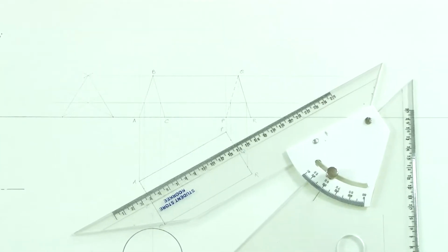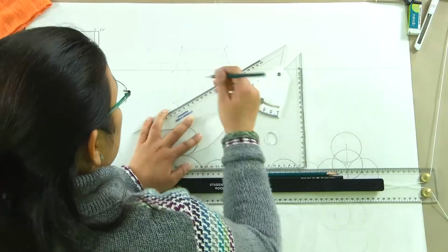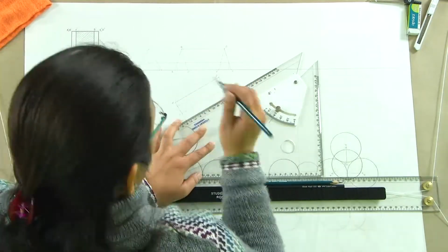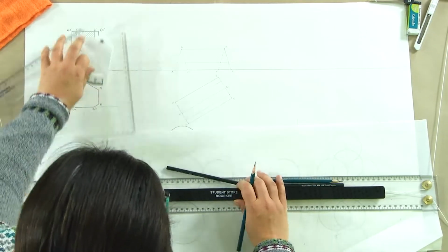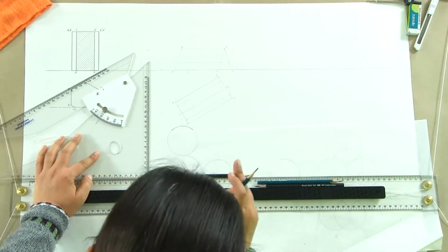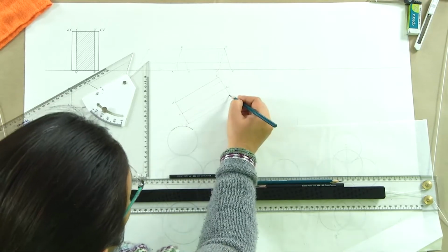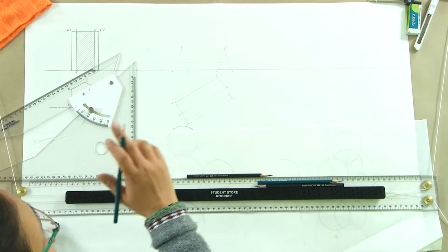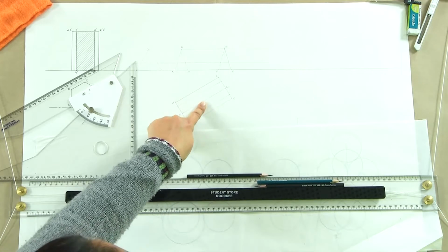And since the plane is parallel to HP, we will actually be getting the straight line here. Ideally, we should be getting. So, if your construction is right, if there is no flaw with your construction here, you should actually be getting the parallel lines. So, again what we are seeing is that we are getting a rectangular section here. It is a prism, and since the plane is parallel to its axis, we will always be seeing this rectangle here, which is exactly what we are seeing.